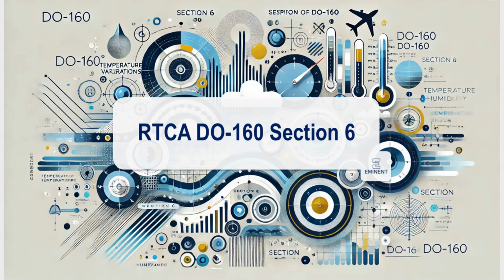Category A. This category simulates high humidity exposure, with testing performed at up to 95% relative humidity. Failures often include corrosion of metal parts and degradation of electrical contacts. Mitigation. Using corrosion-resistant materials, protective coatings and sealed connectors can prevent damage in high humidity environments.